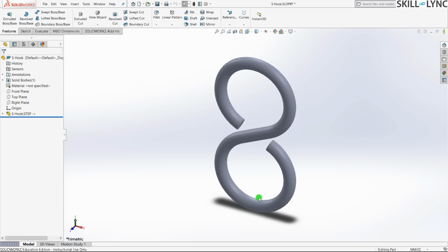So what we will be doing is fixing this area, this place, and this part of our hook, and running a small stress analysis with a certain amount of force acting in this way. Then we will run a fatigue study to determine how many cycles this S hook can experience before it undergoes failure. If you're still wondering where to find this hook, if you have a chain or any gold ornaments, you will be able to find the S hook.